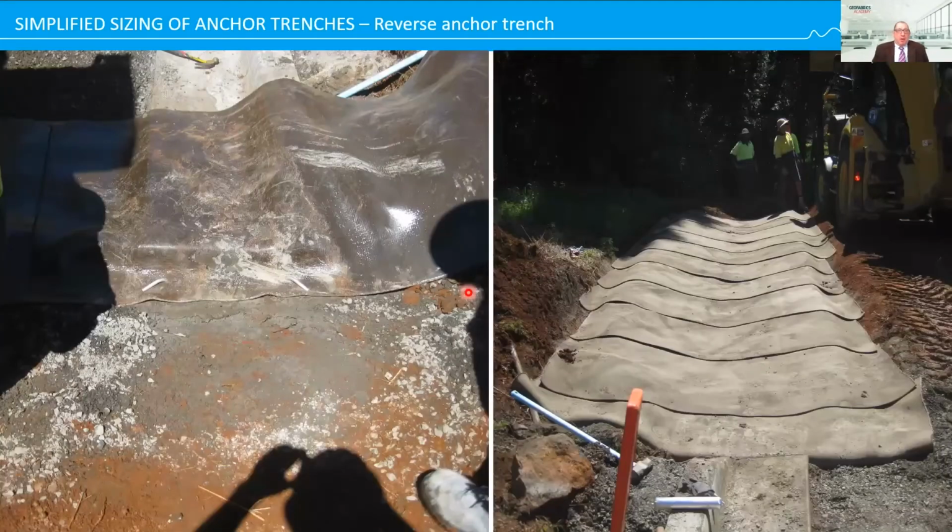All right, here's an example of it here. It's not so clear, but here we have a slip form curb and gutter. For Ballina in New South Wales, they didn't want to put any fasteners through the slip form, so we did a reverse anchor trench. Here's the anchor trench here. It's been pegged in the floor. The Concrete Canvas, this is the underside of the Concrete Canvas material. This is the top side of it. So as you can see here, the GCCM has been flipped over. That'll be backfilled to the right level with the invert of the slip form curb and gutter. Then the material is flipped back over. So we get a nice transition from this curb and gutter down to the swale drain.